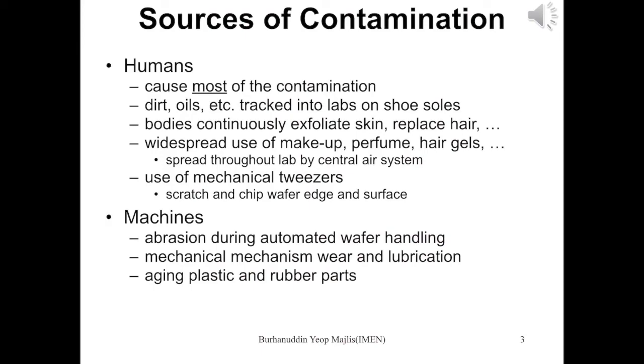The use of mechanical tweezers can scratch and chip the wafer edge and surface. This is from human. From machine, there is abrasion during automated wafer handling, mechanical mechanism wear and lubrication, aging plastic and rubber parts. So this can contribute to contamination in the clean room.